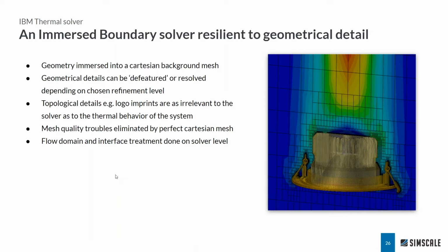And why is this important? Because mesh is by definition closed, so you don't have any problems with leakage. Plus the tolerance is not so strict as on the CAD level, right? Because on the mesh level, you need the tolerance which is essentially linked to your desired fineness of the mesh.